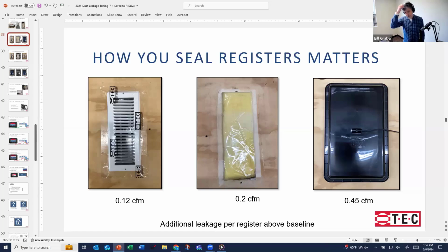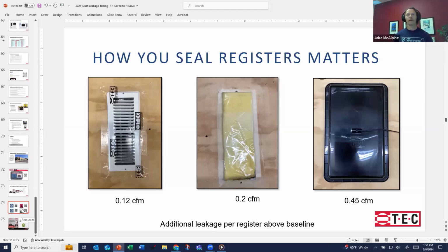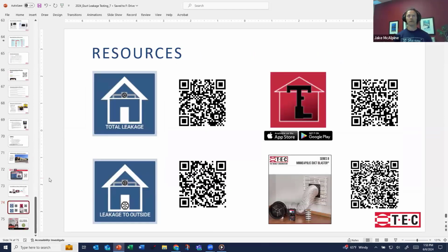Okay. And then it looks like we had one more from Ralph, and it's a good question. It's certainly a deep dive question. He asks, if you've got ducts that are in multiple outside zones, is there a way to ensure that you can get 25 pascals across them? And the answer is that's tough. But you can check it. You can pressurize and check it, and that's what you should do.